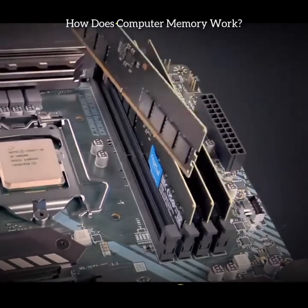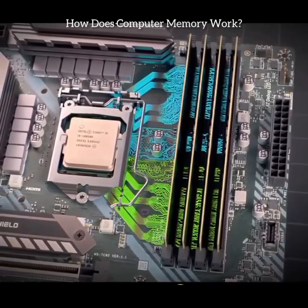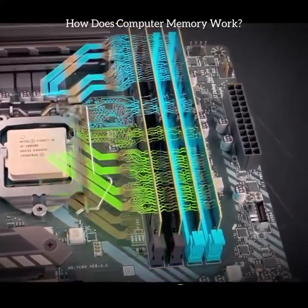On the motherboard, there are 4 DRAM slots, and when plugged in, the DRAM is directly connected to the CPU via 2 memory channels that run through the motherboard. Note that the left 2 DRAM slots share these memory channels, and the right 2 share a separate channel.